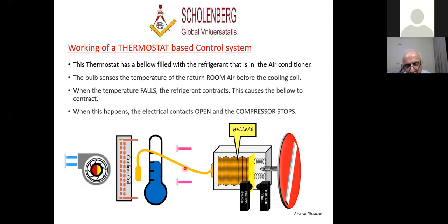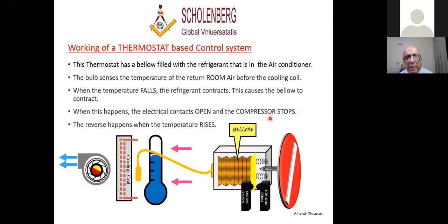You should know, because your machine is not going to work, right? And if you're going to buy a substitute, you should know that you have to have a thermostat or TEV which is suitable for this particular gas. If you have an R22 system, you can't buy a TEV suitable for R410A. Or 134A, you just cannot. It won't work because the system gas and the gas in the controller must be the same. So you ought to know that if this gets leaked or punctured, you have to replace that control. Okay, gentlemen, now we come to the next.